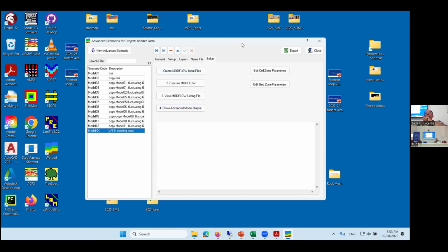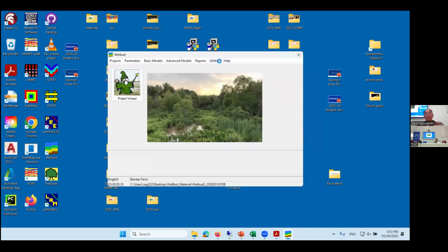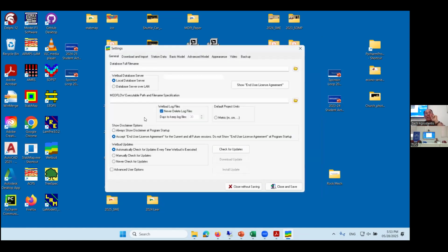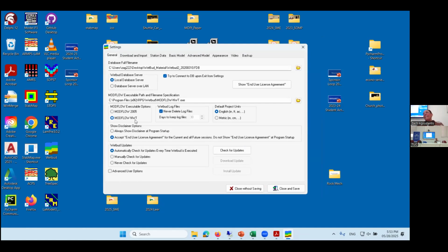Now, it doesn't use the regular solvers. MODFLOW has a variant, which is called MODFLOW-NWT. NWT is for highly nonlinear problems, and it uses that. Why? Because the top layer is water. We are simulating the top layer of water because there's flow in that layer. And of course, if you have an island that's sticking out, that's dry, but the rest can be water. So we're using the NWT solver, which actually converges because the 2005 solver doesn't always converge. Okay.